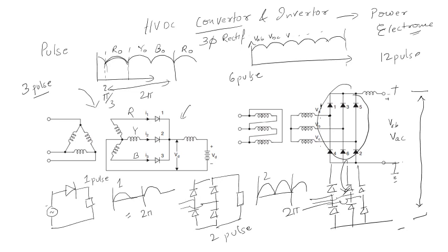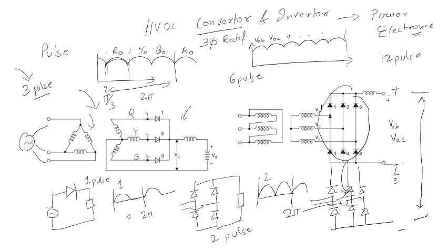So once this is your three phase transformer. Initially this is an AC supply. If you are connecting an AC supply here, and you are stepping down or stepping up using a star delta transformer, and then you are transferring it. So you can use a number of converters. Basically for a three phase supply, we are focused on either 3 pulse converter, 6 pulse converter, or 12 pulse converter, because these three converters resemble more like a DC supply.